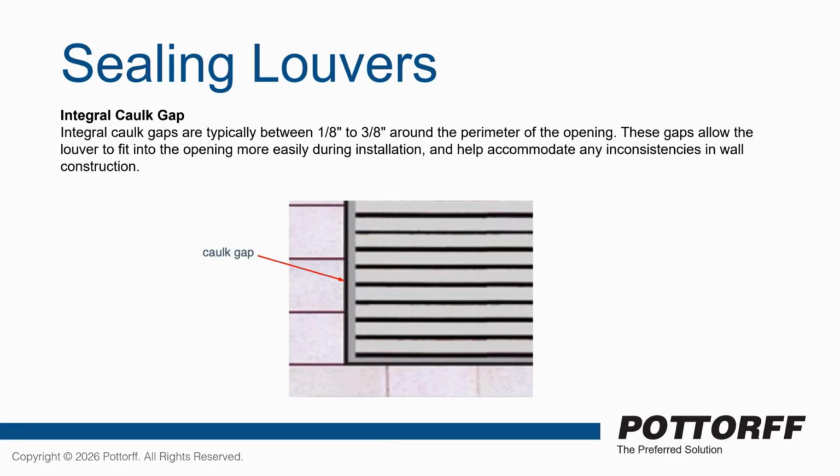Again, that's just any water that's running down the building or any rain coming out from the sky hitting this. You don't want that entering into your building, especially if you have some type of wood connection, right? We don't want that exposed to any type of rotting. So we do require installers, if it's a larger gap, to maybe put some type of backer rod, but some type of sealant over that to protect the louver and the building and protect any water from getting inside that opening.